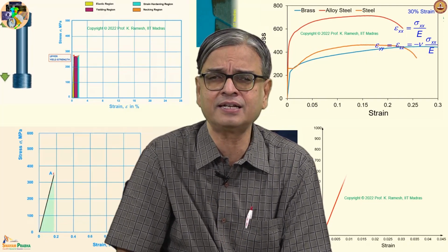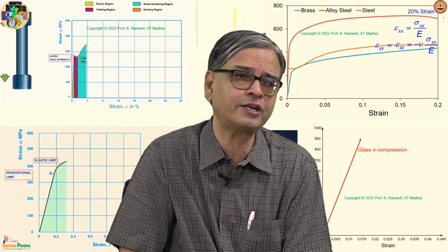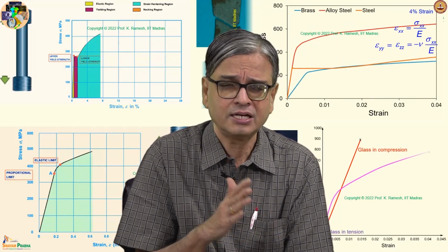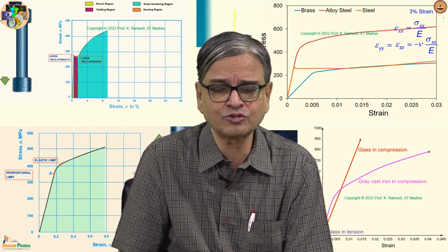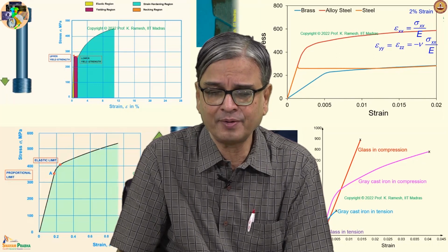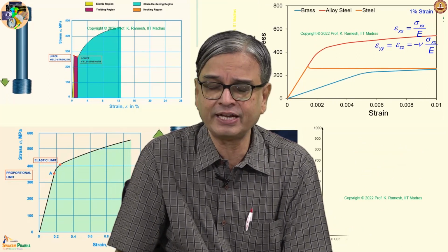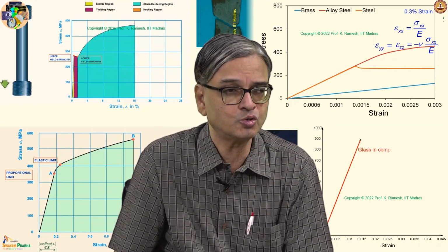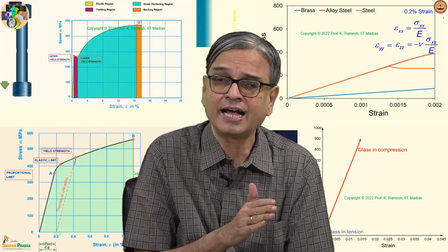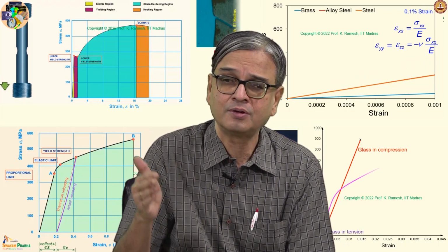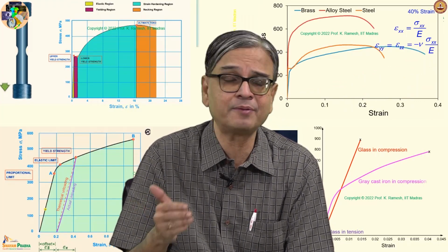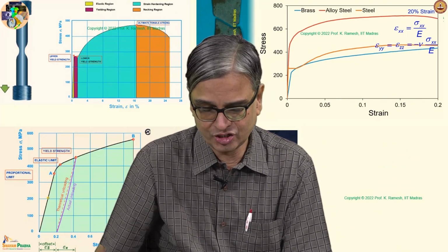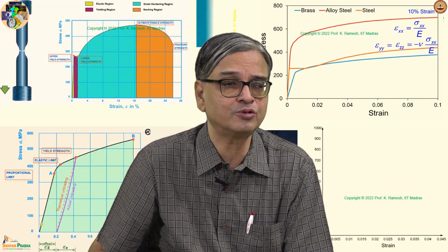If you look at the mathematics, the amount of effort that you put into mathematically modeling, you have the Ramberg-Osgood law, it is very difficult to handle, and for slightly above yielding it is not valid for the complete range either. So, you have to appreciate that as you go and want to model the material behavior beyond yielding, it is mathematically demanding, it is not that simple to do.